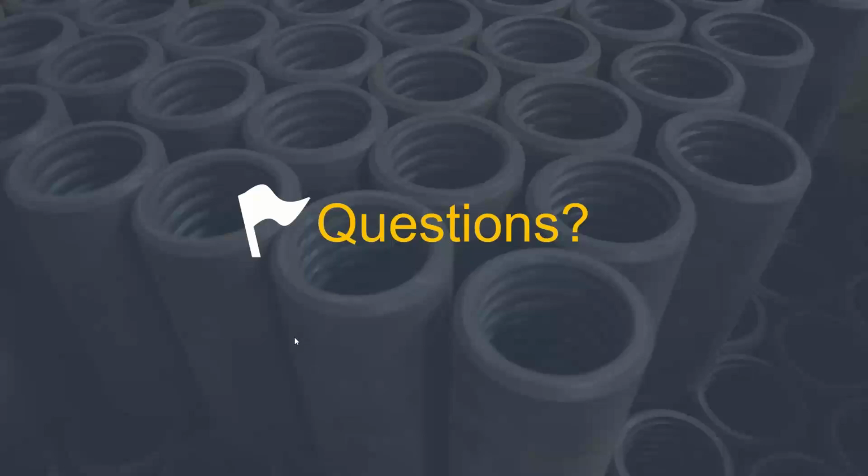Can you explain flexible versus a fixed foundation pile cap? Normally, I don't quite understand flexible. Right. I mean, obviously concrete's not very flexible when you think about it, but it can be if the soil isn't stiff enough or the concrete isn't thick enough.